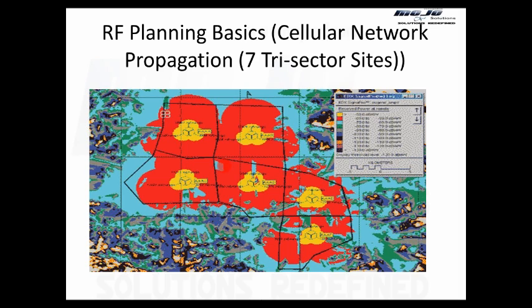But operators don't design their network on the minimum. They come in and they say, okay, for me, the minimum coverage is -95 dBm for RSCP, because below that, I cannot assure the coverage because I want to design my network for given KPIs. In order to assure those KPIs, you have to reach the thresholds of coverage and quality.